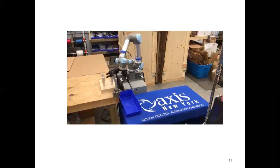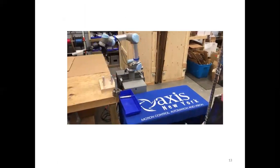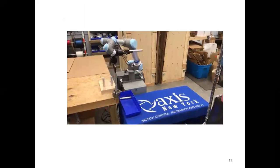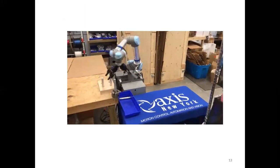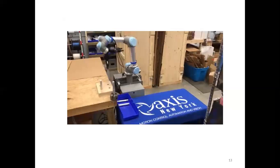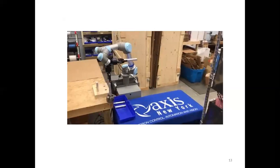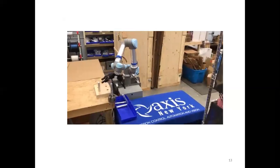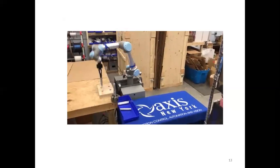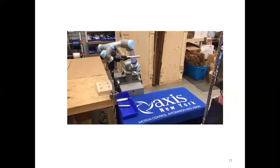Using a single gripper, we are doing multiple operations. If you use a single gripper for pick and place, it will take 2 more minutes. But here, at the same time, it releases the object and picks another, putting the other material in the correct position. So it will reduce the process time by half.